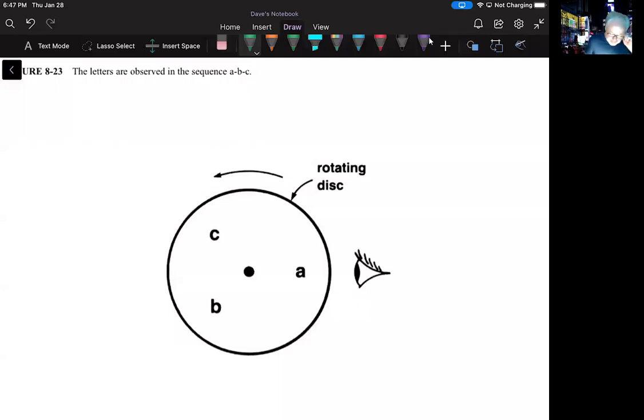So in section 815, he begins, he says, in addition to line voltage and frequency, the three-phase system has an important property called phase sequence, okay? So we want to be familiar with that, phase sequence. It's an important thing for us to be able to deal with. And so maybe we should write it first, right? Phase sequence. And it references in terms of how we would see the various phases as in the rotation of say a three-phase motor.